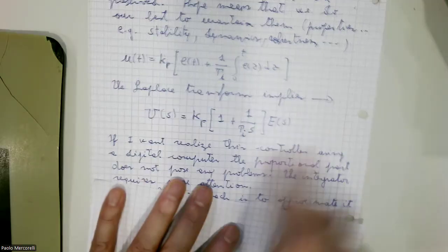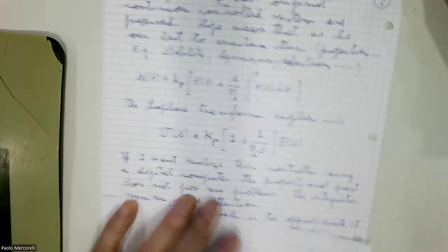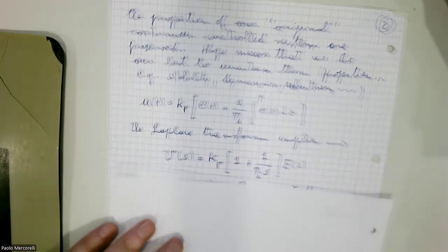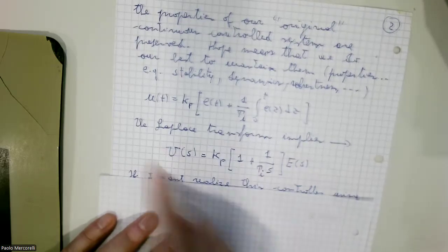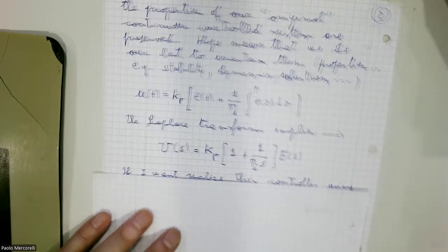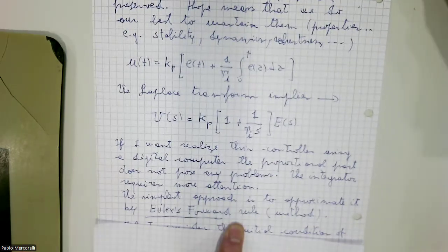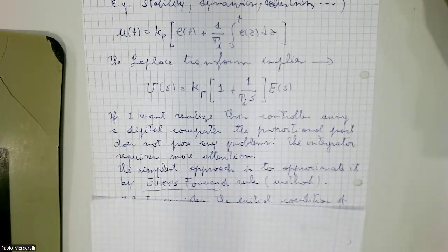Laplace transform of this expression here. At this moment I don't use it directly, but we will see later that this expression here can also help us. Using forward Euler, we will see a little bit the idea which I told you also last time to approximate the PI control. I start with the PI control in order to be more concrete.